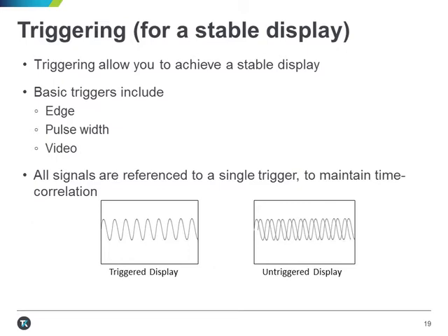The most basic reason for the trigger function on an oscilloscope is to allow you to stabilize the trace on the display. The oscilloscope's trigger function synchronizes the horizontal sweep at a specific point on the signal, and the trigger control sets that point. This is especially important for analog oscilloscopes that cannot store individual traces. With an unstable trigger, the signal becomes jumbled on the screen since the drawing begins at a different part of the waveform each time. This is the picture on the right.